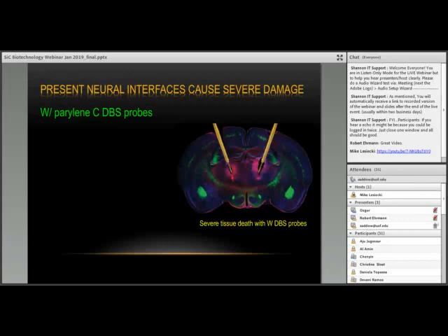And so our goal is to replace, in this case, tungsten metal wire electrodes coated with parylene C, which is a quite nice biocompatible, neurocompatible polymer, with a much more durable material. Silicon carbide, by the way, is a ceramic. The stuff is extremely corrosion resistant and resistant to the harsh environment of the body, and that's what I want to leave with you today.